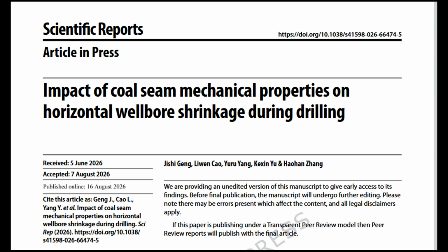Equation 3 gives the strain displacement relations for the axisymmetric case. The tangential strain is the logarithmic change in radius, how much the circumference stretches, and the radial strain is the logarithmic change in thickness of a concentric shell. The use of logarithmic strain is essential because the model deals with large finite deformations, not just small elastic strains.